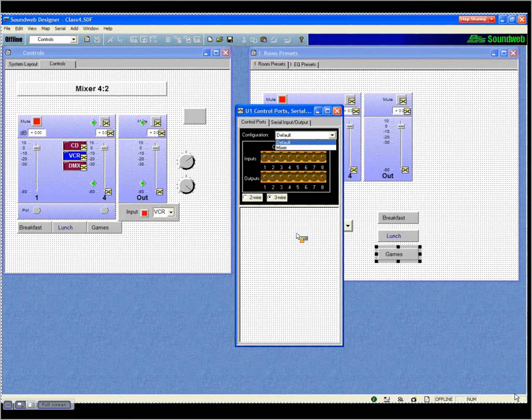By the way, it makes it real easy to create a control port to toggle between 2 or 3 or 4 configurations. Just in every configuration, you put a momentary contact button on input 1 that triggers the next configuration. Now, it's not a button you want somebody leaning against, so don't put it at shoulder height in your control booth. Kind of a well-duh situation.